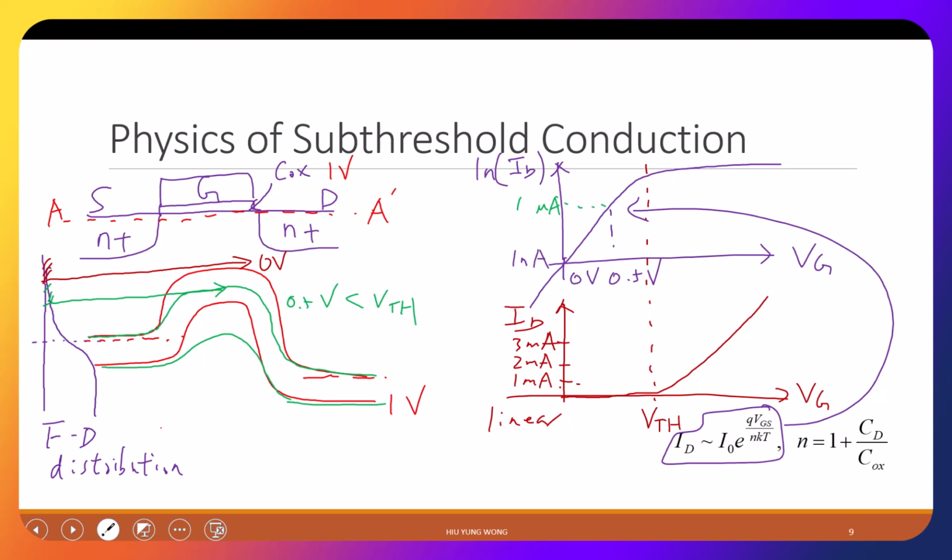Is this the same thing that happens as our... Exactly. And if you remember, this is similar to the diode equation, remember? It's a good question, because you should understand this is like a diode, right? For a diode, if you remember, it is something like this: ID equals I0, some fundamental leakage, right? E to the power VD divided by VTH, which is the thermal voltage kT over q, right? And then minus 1. When your VD is large enough, this is basically the same. It means you go up exponentially, right?